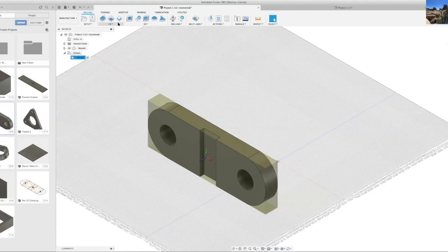By adaptive, do you mean, for instance, if you did a large clearing operation with a 1/4-inch end mill, and you needed just to clear a few pockets with, say, a 1/16 inch, it would know just what to do for that one remaining portion for the 1/16 inch mill? It does a roughing pass, figures out how to do the roughing pass, and then it asks you how much material you want to leave for your final pass. Yeah. And it comes back and does a really clean final pass.